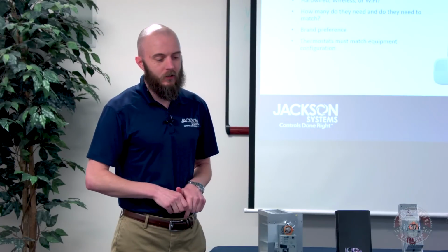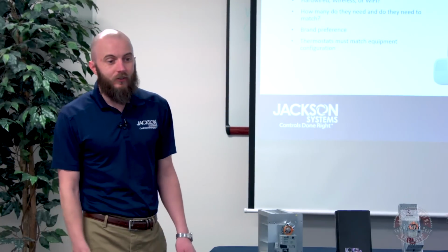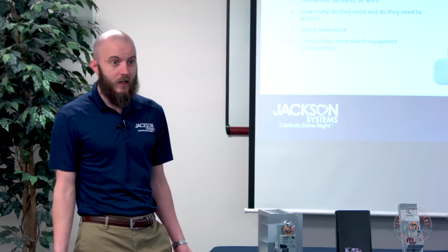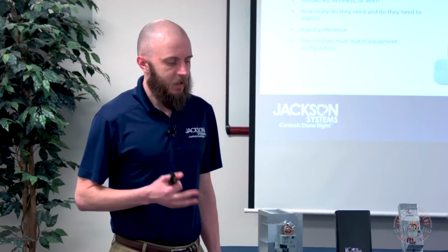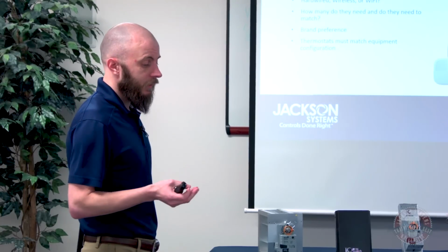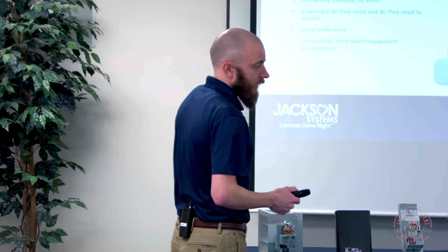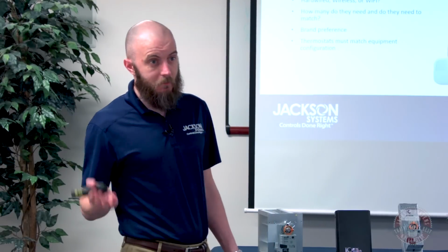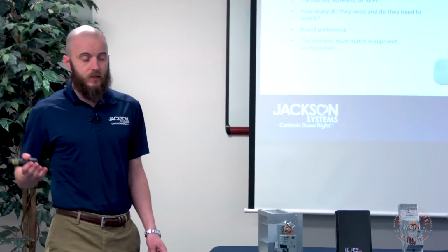So first of all, if your ECM blower is capable of dealing with the increase of static pressure on its own, you may not even need a bypass. Depending on how a system's set up, if your zones are fairly equal, and depending on your duct size, and there's a lot of variables here, the amount of static pressure you need to relieve isn't always that much. Sometimes it can be, sometimes it's not. Like I said, every situation is different.